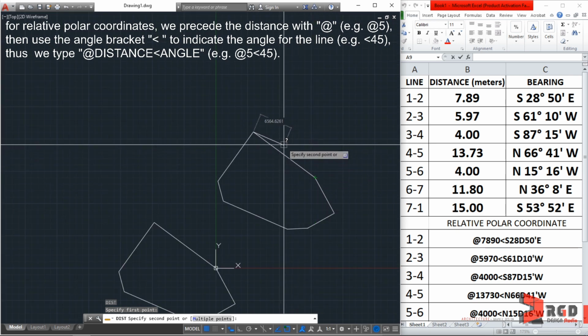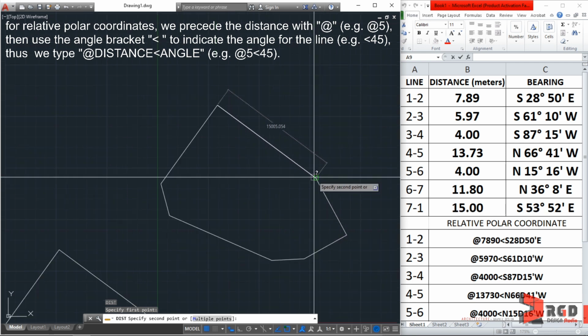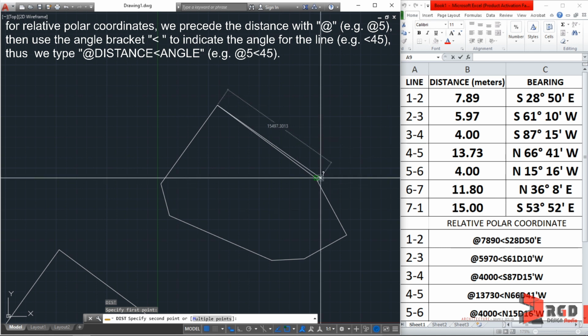So a while ago we closed this one. We did not input these coordinates. Okay, so obviously when you use this coordinate and distance, I mean bearing and distance, this will not close. So better don't use this, just close your geometry for precision in AutoCAD. Okay, because I repeat, geodetic surveys are allowed with a margin of error of around 8 inches. Okay, so if you have boundary issues, blame that to the geodetic engineers.